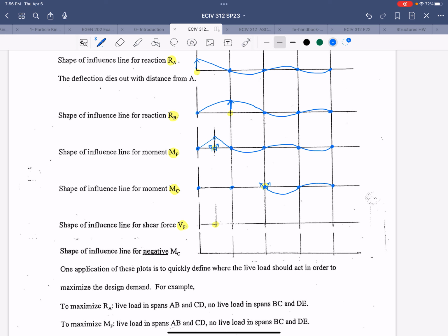We have curved lines because if we isolate this segment, all right, we'd have a roller support here, a roller support here, and a roller support here. That is vertically stable on its own. On the left side, if we isolate that segment, we have 3 roller supports, which is vertically stable on its own. So this will also be straight line segment, curved segment. And that counterclockwise rotation will also force it to deflect downward.